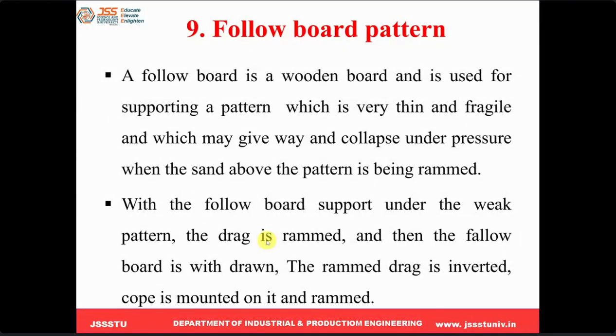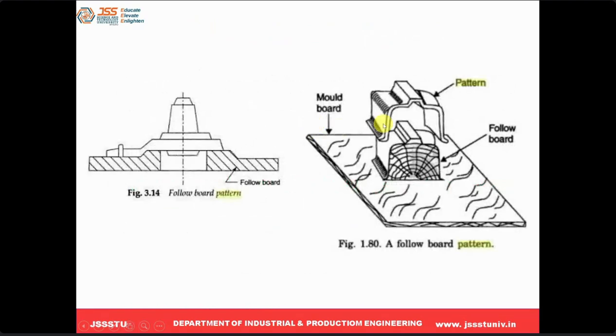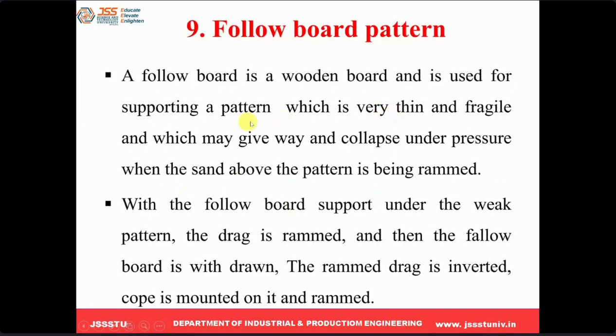And the last one is the follow board pattern. A follow board is a wooden board which is used for supporting the pattern, which is very thin and fragile. I think you can see the follow board. So here, what is this follow board used for? You can see, this is the follow board. Basically the follow board is used for supporting a pattern which is very thin and fragile.